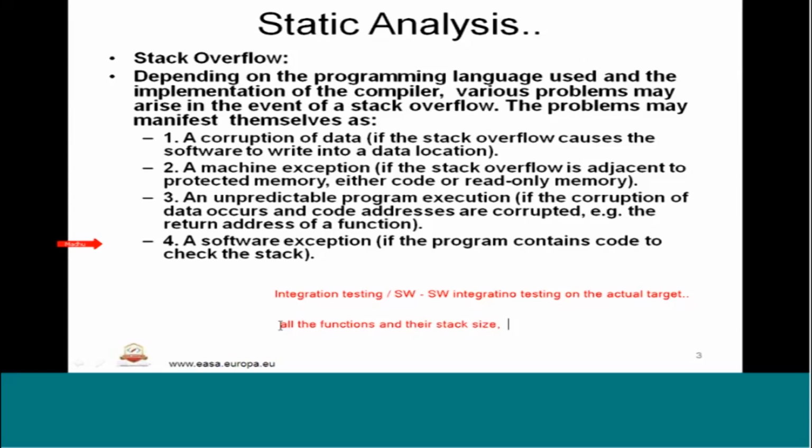So stack analysis will be done, and we need to combine all the data during this worst case stack execution. This will definitely be done at the source code level, basically by counting the size of all data declarations and parameters. We don't need to do it manually. There are tools that will report the size. The size needs to be analyzed.